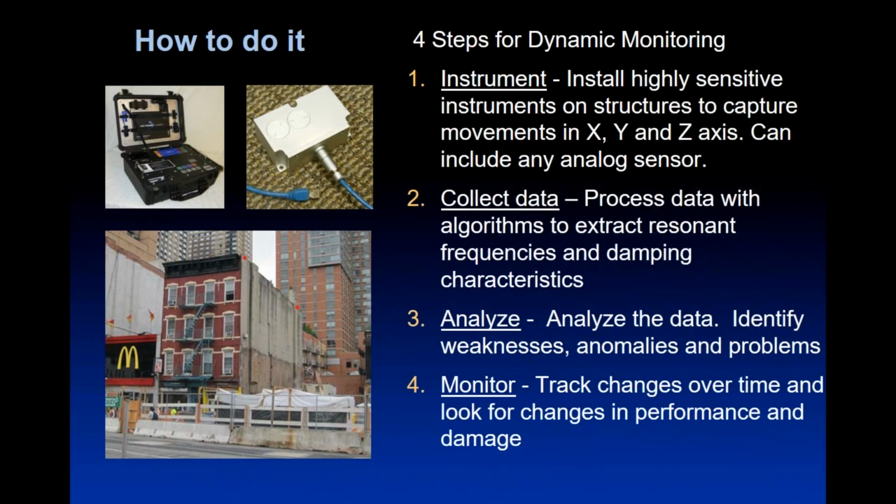This is a box which has been ruggedized. It's useful for use on site, and it allows somebody to go on site, connect accelerometers to it, and make measurements over the required time. The required time depends on the random response of the building to excitation, and we can calculate that within 10 minutes of being on site.